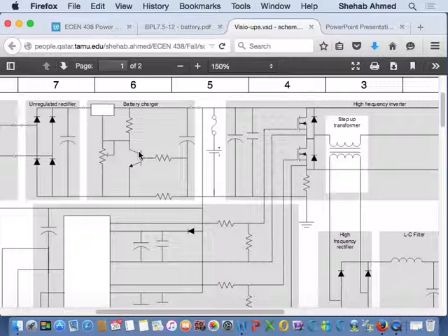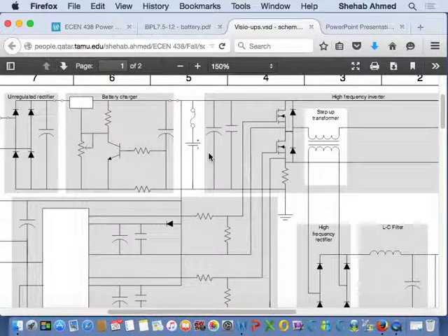This is how I use it. This is how I design it. It's in there. So now I'm supplying my battery. Right, so I supplied my battery with a constant fixed current, and then this control circuit here sort of disconnects and stops the charging whenever you've hit the limit of the voltage. So it's a small control circuit. The data sheet of the LM device will tell you how to design it, right?